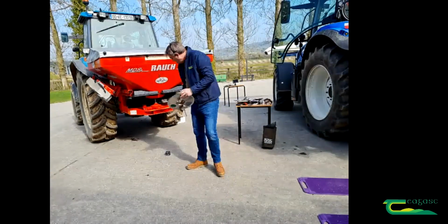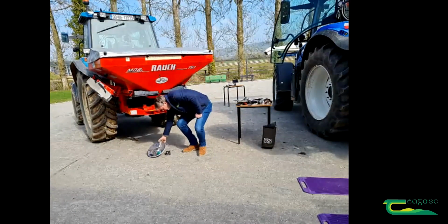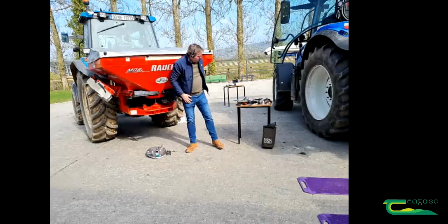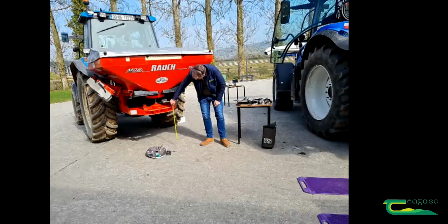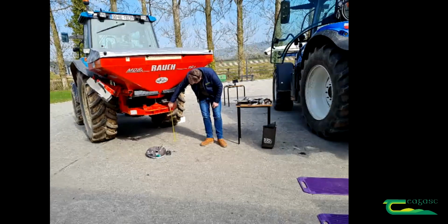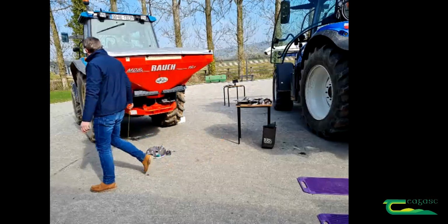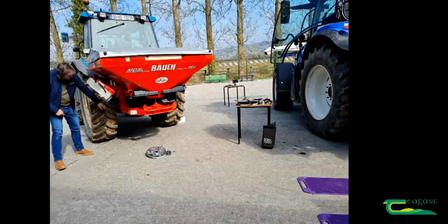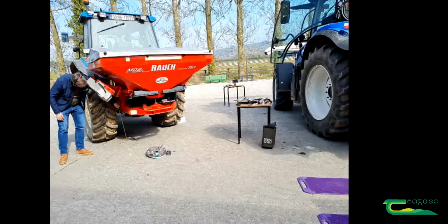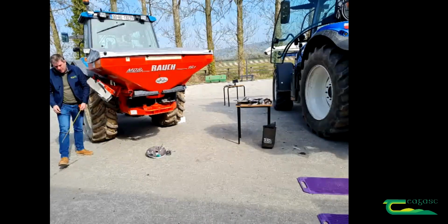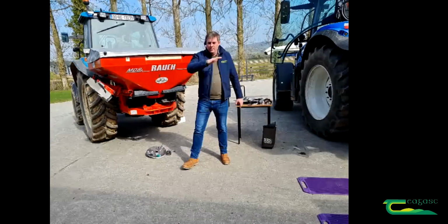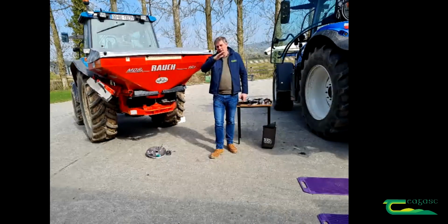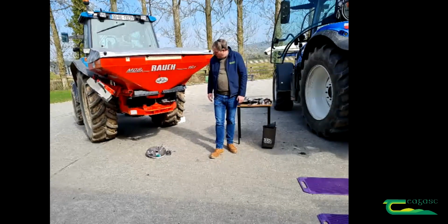The other item that we mentioned was our operating height. So again, it gave us an operating height. In this case, it was saying 60. So again, we're measuring from a tab here on the back of the machine for my rear measurement, and my front measurement is taken from this tab in here, okay? But as we mentioned there, this was 60-60. But you will find in top dressing that measurement will actually change and will lift the back of the machine that bit higher, okay?